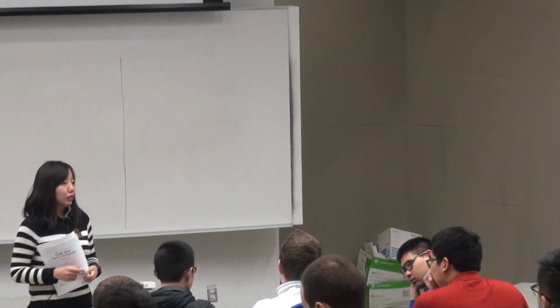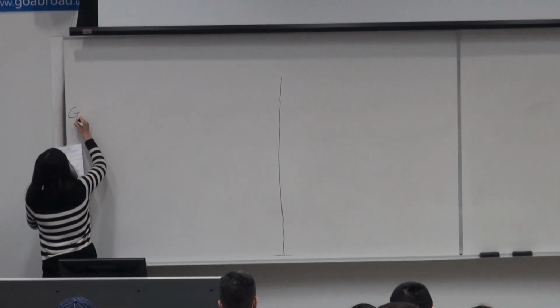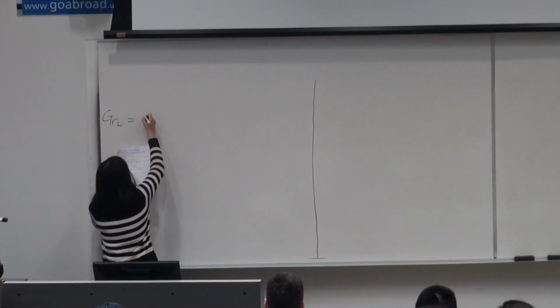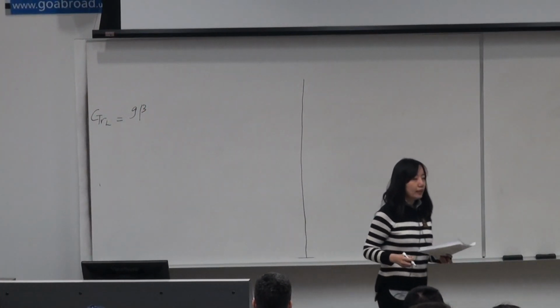And we talked about laminar free convection on an isothermal vertical plate and the development of both the viscous boundary layer and thermal boundary layer. Similar to external flow, free convection also has a laminar region and a turbulent region. What's the critical number? Then we discussed 2 new dimensionless parameters. The first one is the Grashof number, which is the measure of the buoyancy over that of the viscous effect.